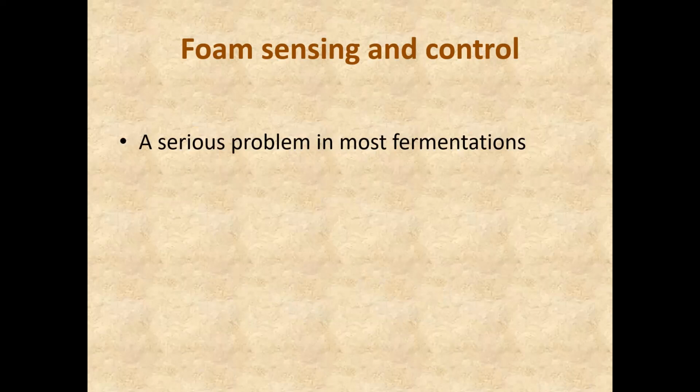Now, why does foaming occur in a fermentation? What is the cause of foaming? It may be due to a medium component or some factor produced by the microorganism. The most common cause of foaming is proteins present in the medium, that is, a proteinaceous rich medium such as corn steep liquor, pharma media, peanut meal, soybean meal, yeast extract or meat extract.